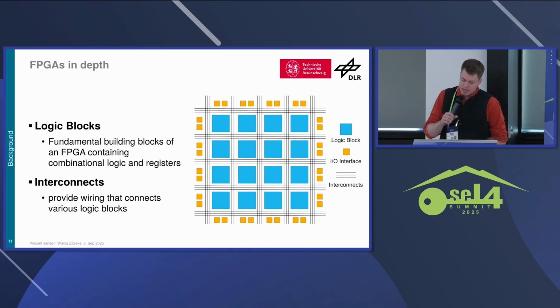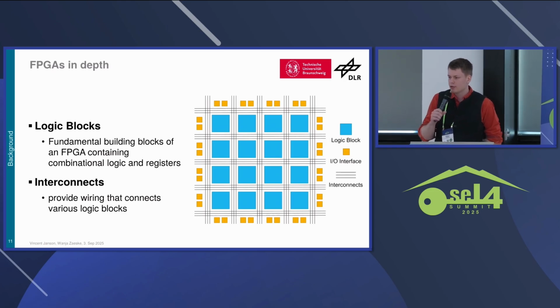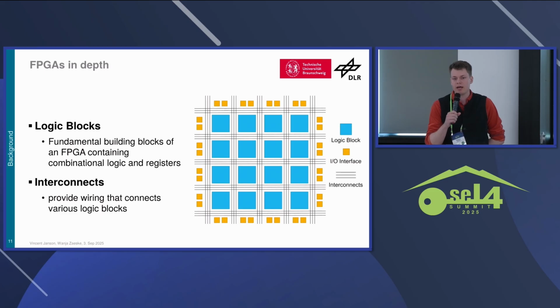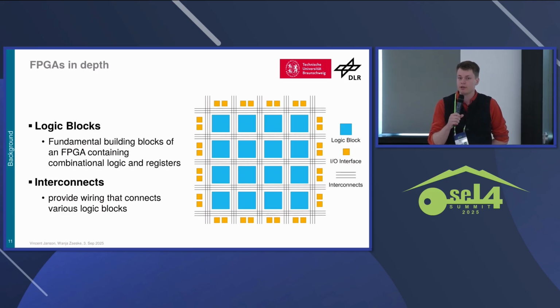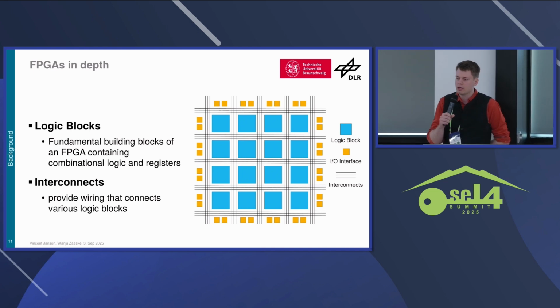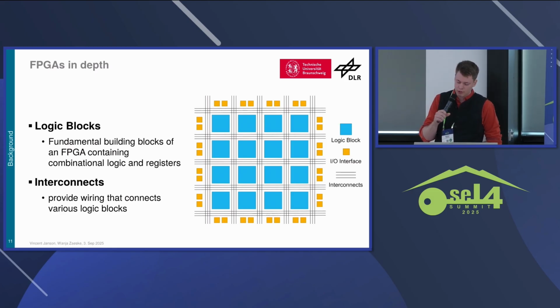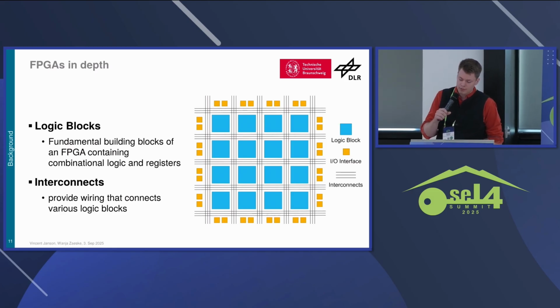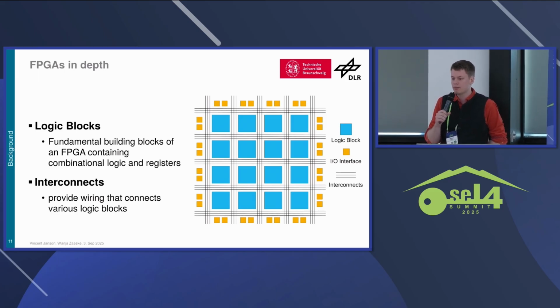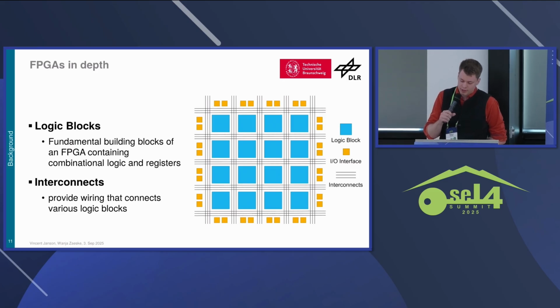So the next point, in the title we had something about reconfiguration, and that is one ambition that we have. We want to be able to reconfigure not only in the software but also in the hardware what kind of accelerators we're running. A reason for this could be that we have, for example, two different sets of AI applications for computer vision. Think about the collision avoidance in the air. Quite likely we cannot fit all accelerator cores that will be needed at some times in the system at the same time into the FPGA, because it only has a limited amount of gates. And thus we want to be able to reconfigure the FPGA.